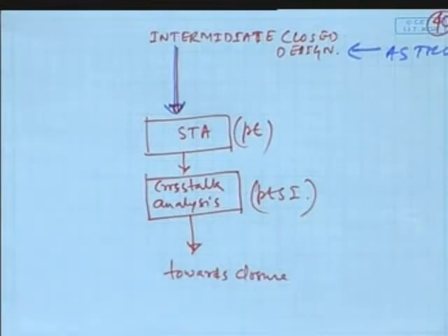It doesn't calculate the whole delays; it calculates a delta delay effect due to the crosstalk. You incorporate that delta delay, run the equations once again, and if it is violating, you report it, otherwise you say it's not violating.